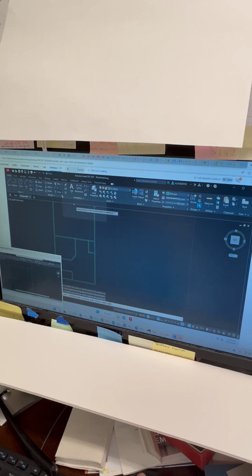So start the offset command. I want you to put in here 2'6" as your dimension, 2'6", and hit enter. Then here's the tricky part. You have to select the object first. So select the lower line of the wall that divides the two rooms, the inside face of the closet, I guess you could say. I'm going to move my mouse well below, in this area here. Oh, but first I have to start the multiple option, of course. That's the whole point.